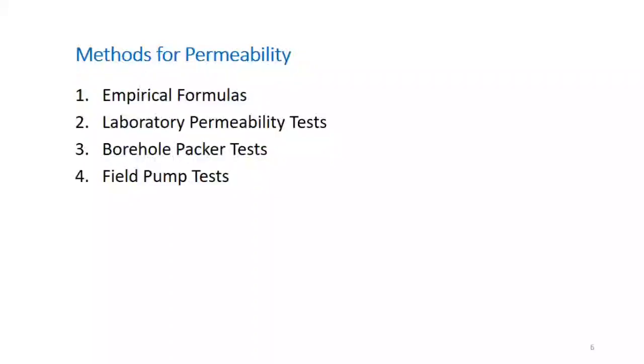Having no confining stress is itself a source of disturbance, which can cause swelling of the soil. Once the soil swells, its structure and void ratio change, so the permeability is going to be different. That's why mostly we do not perform laboratory tests on soil samples retrieved from the ground. Rather, we make reconstituted soil samples in the lab at a given density, a given moisture, and a specific void ratio, and then you can somehow replicate the field conditions and get the permeability.